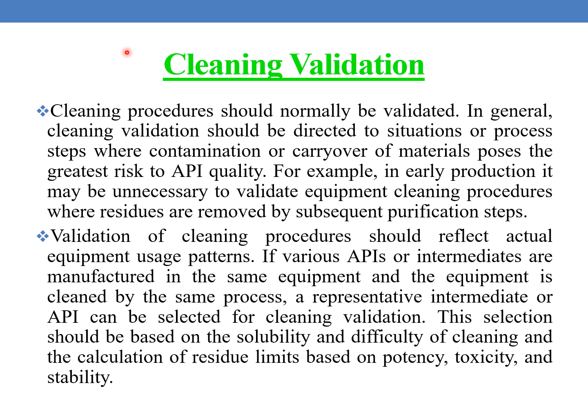Coming to cleaning validation. Cleaning procedures should normally be validated. In general, cleaning validation should be directed to situations or process steps where contamination or carryover of material poses the greatest risk to API quality. For example, in production, it may be unnecessary to validate equipment cleaning procedures where residues are removed by subsequent purification steps. Validation of cleaning procedures should reflect actual equipment usage patterns.